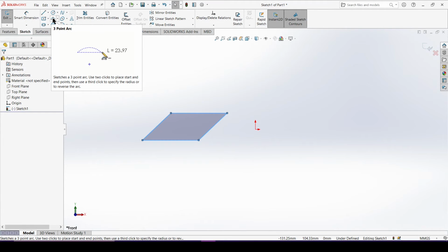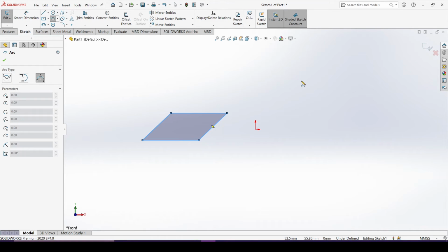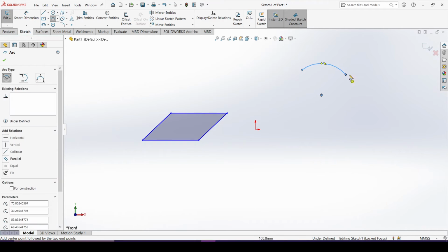Okay, so in this we'll be creating partial circles or arcs. First method, simplest one, we just need to specify the center. First click will start the arc and the second click will end the arc. You can also do it this way. There are a lot of ways of doing this, no problem. There we go. End the arc. That's it. Let's go to the second method.